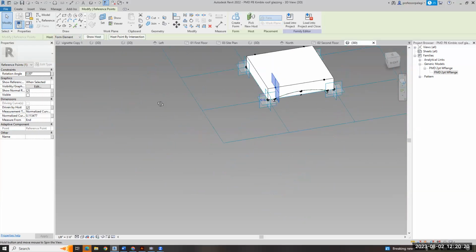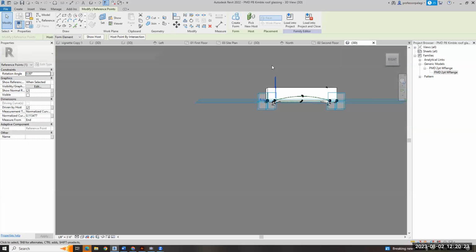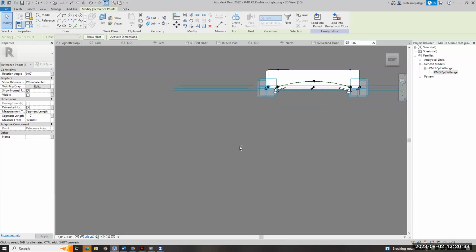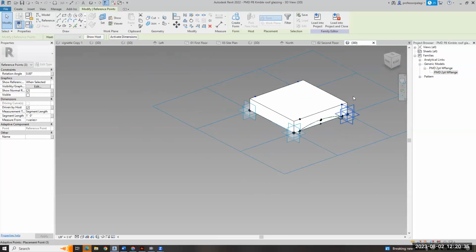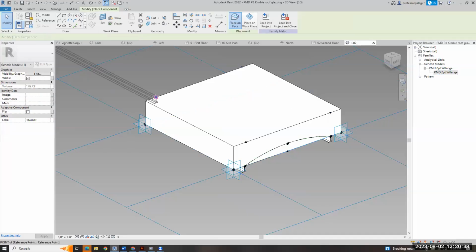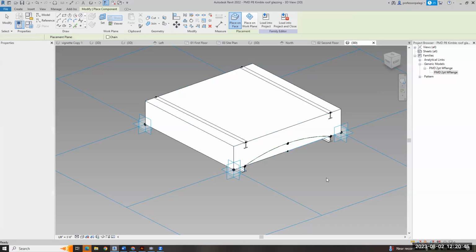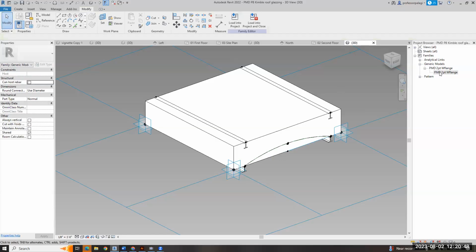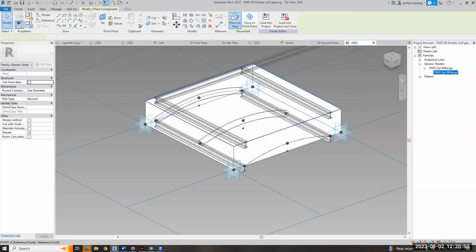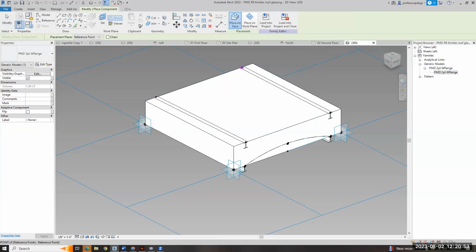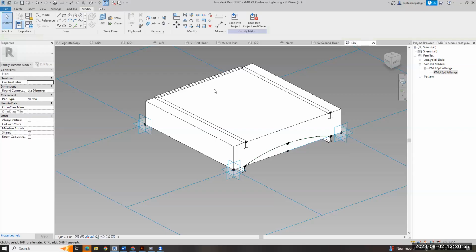Okay, so now they're all facing the same direction. I can sweep grab that way, probably get all 4, and then say I want segment length. I want this to line up directly over the top, which was 1 foot, right? I want to bring that same W flange in because it is actually just a stacked element from there to there, and another one from there to there. And then, hey, but let's just not even be fancy about it. Let's just put another one in from here to here.